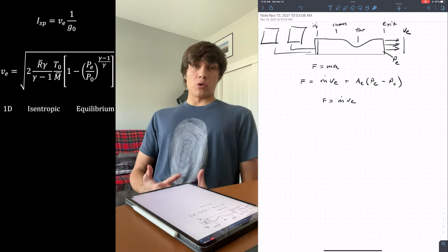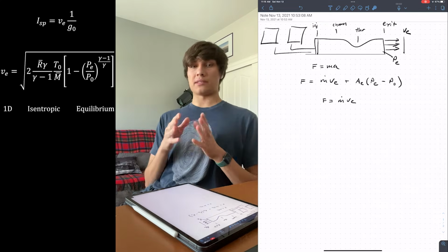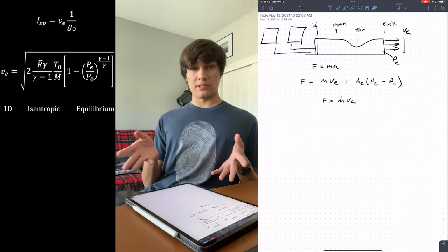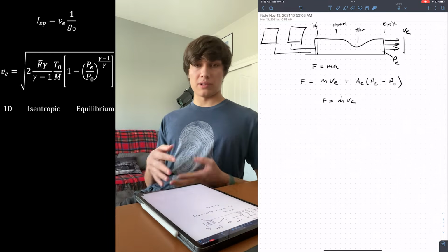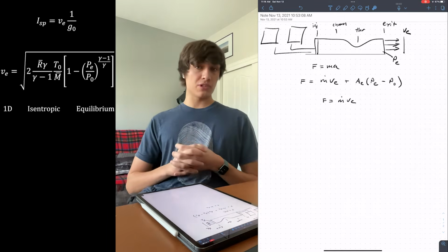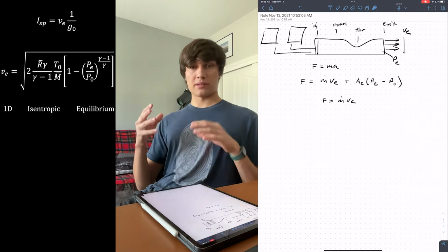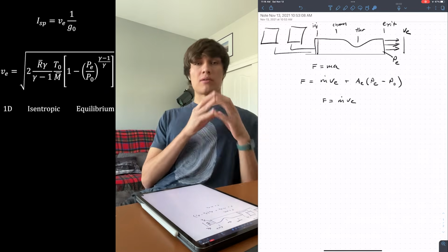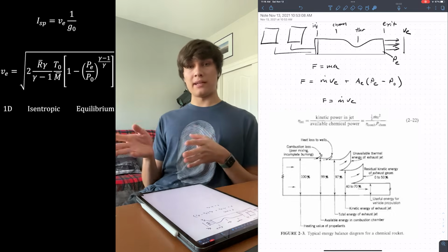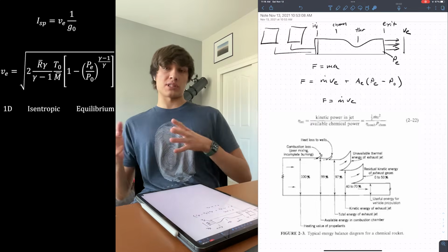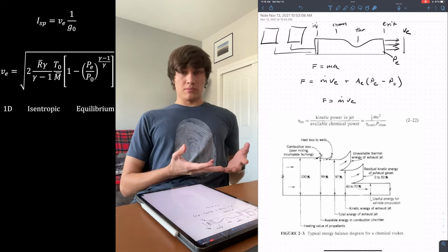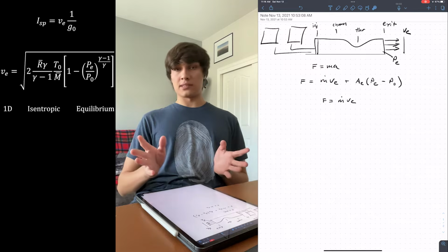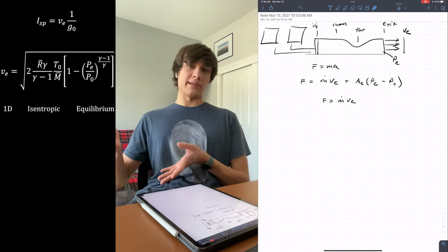The reason that the isentropic assumption holds is a question of relative scales. The amount of heat that is conducted out of the flow is small enough to be relatively negligible. If you're familiar with the concept of isentropic efficiency, which is the difference between a fully ideal isentropic flow and the inefficiencies or losses that occur, a rocket engine's isentropic efficiency is somewhere between 0.98 and 0.95, according to Sutton. We're going to get close to what's actually happening inside the rocket engine if we assume that there's no heat conducted and there's no irreversibilities in the flow. Remember, this is okay for sizing the engine, and then you will stray away from the idealization as you go further into design.